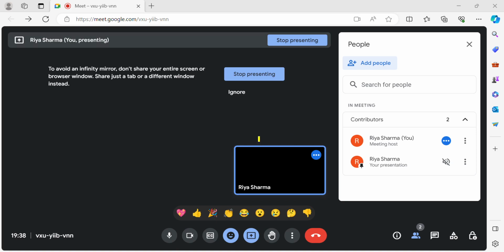So basically, Z is that factor. When Z equals 1, PV equals RT, it will follow an ideal gas. Otherwise it will tell you the ratio or the change, V actual by V ideal. The compressibility factor is unity when there is no deviation from ideal gas because it is an ideal gas. For real gases, it can be equal to 1 or greater than 1.